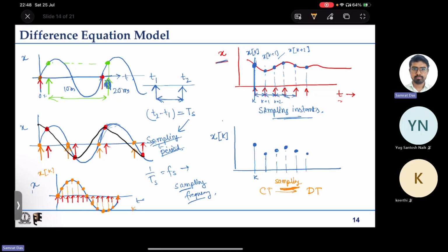But you saw that if the signal is of 50 hertz, and if we sample at 100 hertz, still the information may not be sufficient. Like these red dots, we were sampling at 100 hertz, but we could only say that there is some variation from positive to negative and positive to negative, but we did not have accurate information of the system.